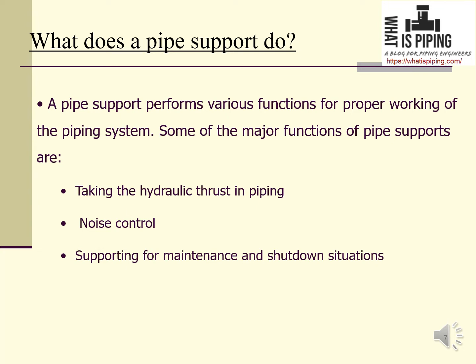Noise control: by reducing or absorbing the vibration or acoustic measures, we can reduce the noise also. And supporting for maintenance and shutdown situations. During maintenance and shutdown situations, there could be a requirement of additional supports. So proper supporting will help in proper shutdown and maintenance philosophies.